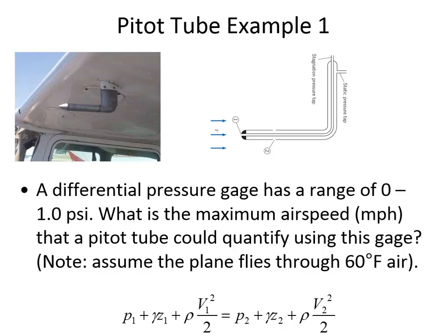And these are traditional units, and you'll remember that a slug, there's 1.94 slugs. What's the conversion? 32.2 pounds of force is the same as 1.94 slugs. Oh, no, 1.94 slugs is the density of water per cubic foot. So the density of air is much less than the density of water. We can find gamma as the density times g, where we'd use 32.2, to get 0.0764 pounds of force per cubic foot.